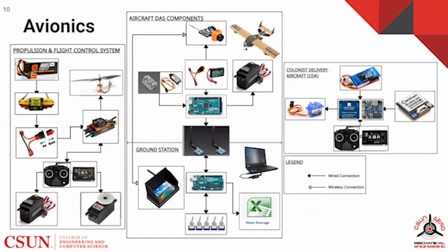The second circuit features a data acquisition system, the first-person view, and payload release servos. The Arduino-based data acquisition system measures altitude, speed, and payload data, and transmits this information to the ground via an RF link on the ISM band. The flight data is then displayed and stored via an Excel-driven graphical user interface.